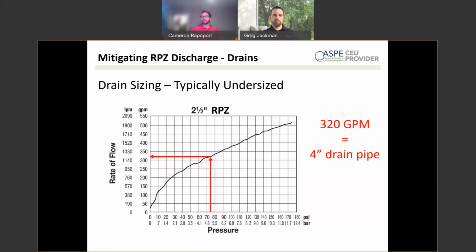So this is a worst case scenario. This is with basically nothing in the way. A check is destroyed. Water is freely flowing out of the relief valve. But it does happen. It gives you an idea of what could potentially occur if you get something big stuck in that first check. So one, using a strainer at least keeps the big things out. If big rocks cause big leaks, small rocks cause small leaks.